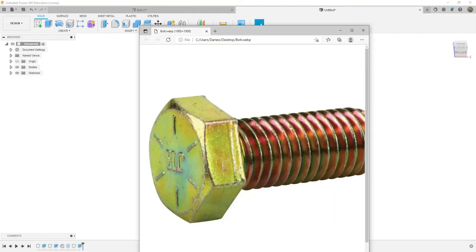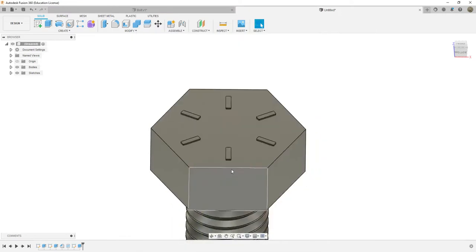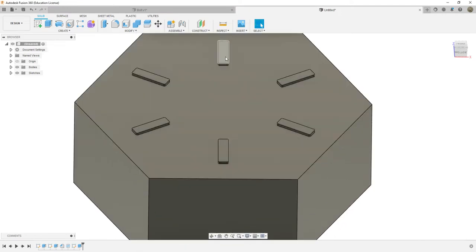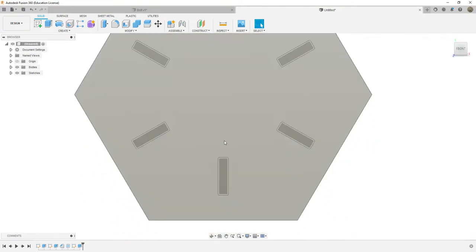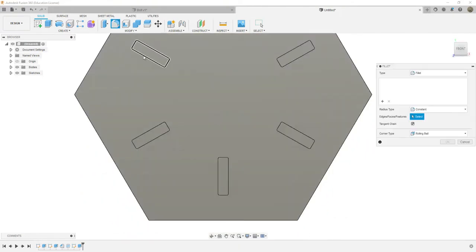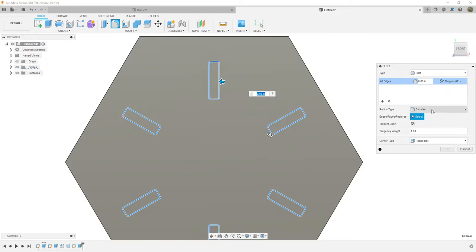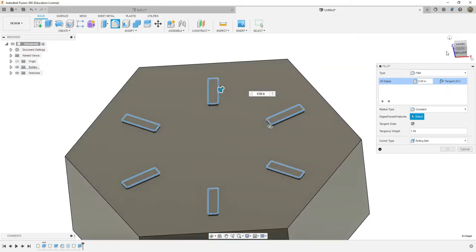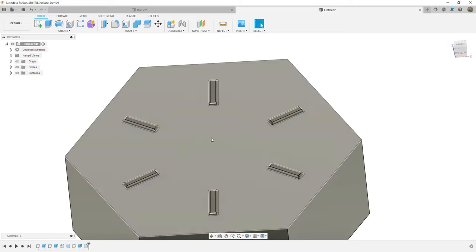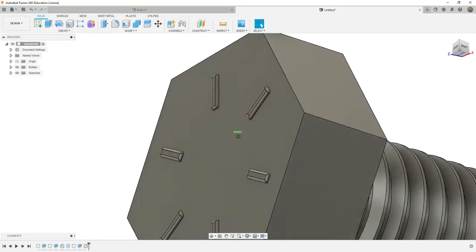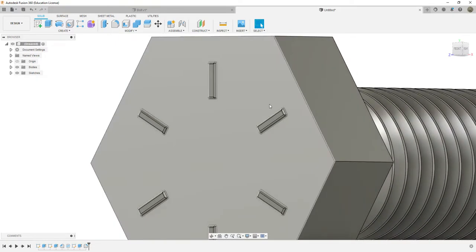So if you look at our picture, we're getting close to how they are. They have their edges all filleted. I'm not going to make you do that, but if you wanted to and you have extra time, what you could do is go in and do the fillet and select all these. And then type in a small number here. Let's see, 0.01 is about how high we rose them up, so that makes sense to do a 0.01.